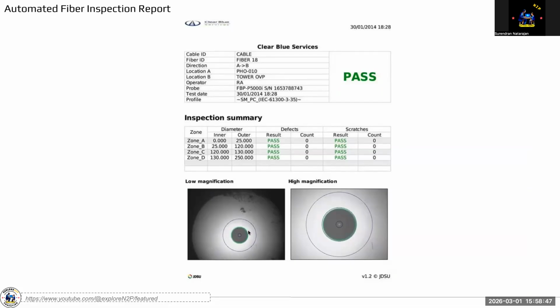If you have dust here, it will hit your fiber optic light, because if there is small dust or a water particle, then the light starts deviating. So you need to see this, and the fiber video scope should show that it is a pass. Otherwise, it will not.